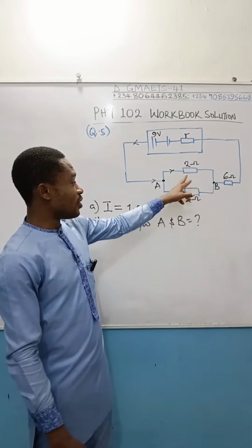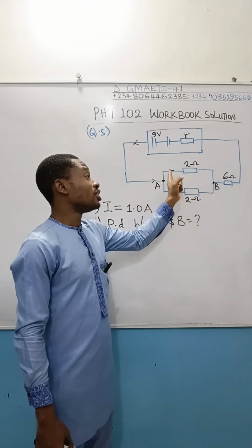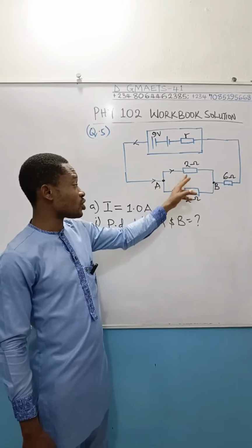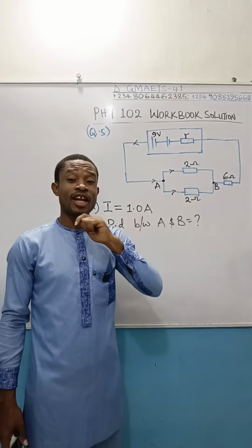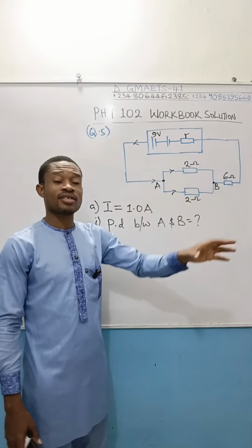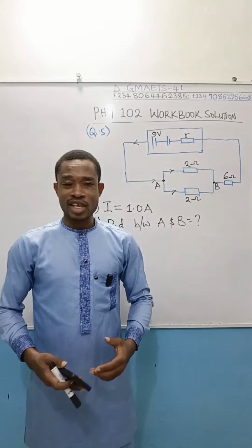However, if the resistors, like in this case, are the same, although the current will share here, the same current will flow through them. That is just a coincidence here because these 2 resistors have the same resistance value. Otherwise, generally, a parallel connection divides current, and it is expected that the current will be different. I hope I'm communicating right.